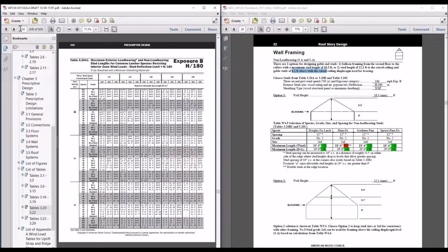Let me jump to page, sorry, I told you wrong. Let's jump to page 233 because the wind loads span across 2 pages, so we can get it all on opposite pages. So 233 under 160. We're going to jump down here and again look at a Doug fir larch number 2 because it's the first one in the table. And let's see, 12 inches on center, Doug fir larch number 2, and it's a 2 by 6. Why is that showing 19.5? 19.5.